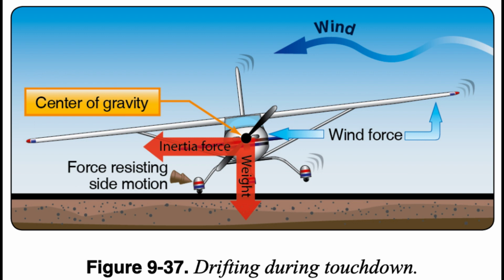If the upwind wingtip is raised by the action of this moment, all the weight and shock of landing is borne by one main wheel. This concentration of forces may cause tire failure or structural damage. Not only are the same factors present that are attempting to raise a wing, but the crosswind is also acting on the fuselage surface behind the main wheels, tending to yaw, or weather vane, the airplane into the wind. This often results in a ground loop.